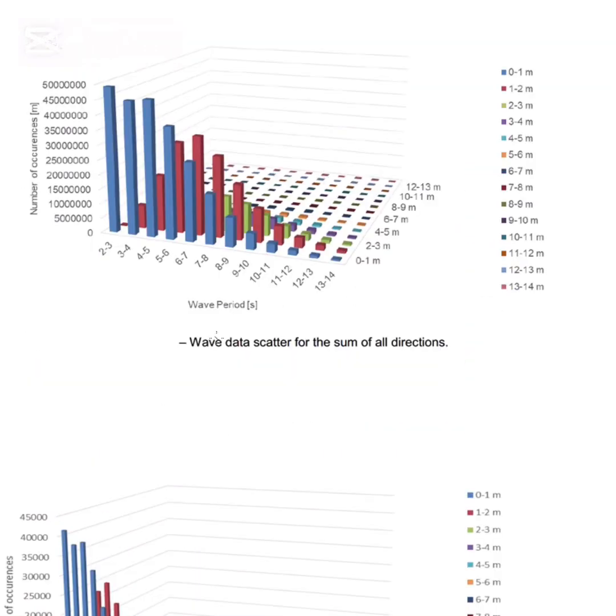If you see this is the wave scatter diagram. Here you see how many occurrences are happening. It's like millions of cycles are happening, and we have the wave period and wave height. This is significant wave height and zero crossing wave period or peak wave period. So from here, what we observe is that most of the occurrences happen with 1 to 3 meters, and with periods of 2 to 3 seconds, it's a high frequency, happening too much for this frequency, with fewer large waves.